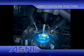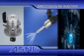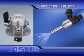This means that the cheaper produced plastic-bodied injectors and aluminium-cased fuel pumps have now been replaced by high-pressure stainless steel fuel pump and injectors, both designed to deliver very precise quantities of fuel at extremely high pressures for minute durations of time, in some cases fractions of a millisecond.